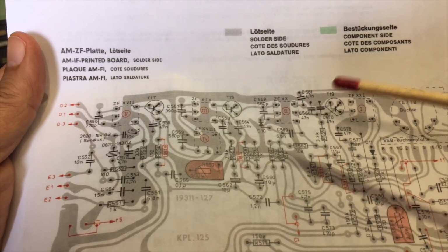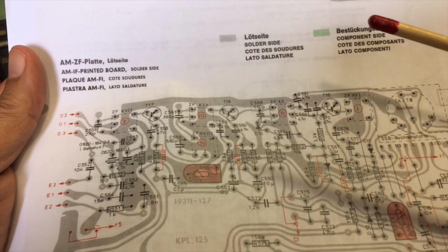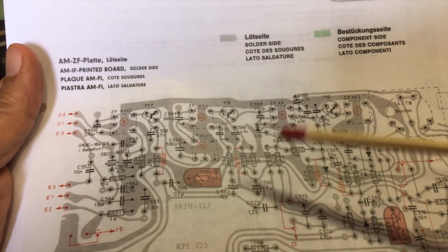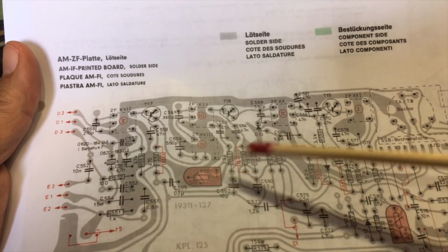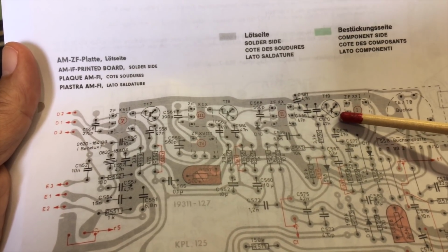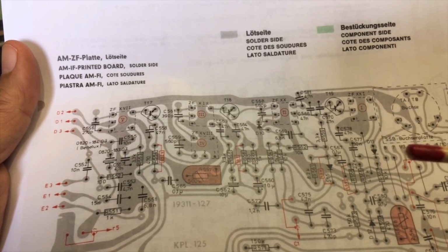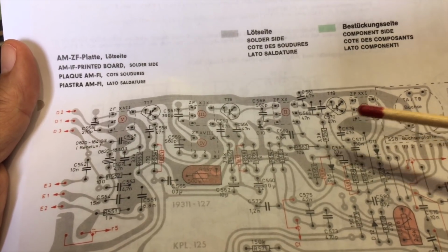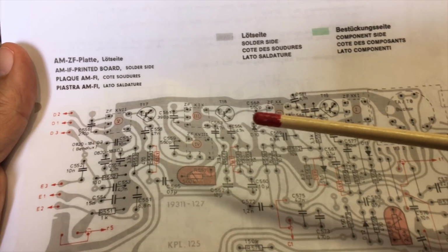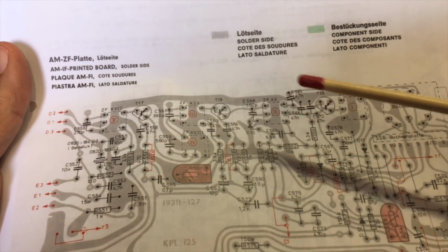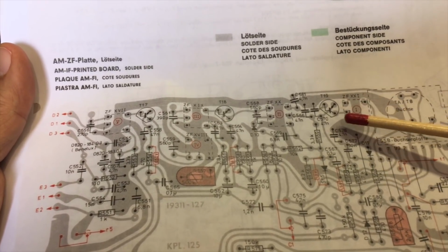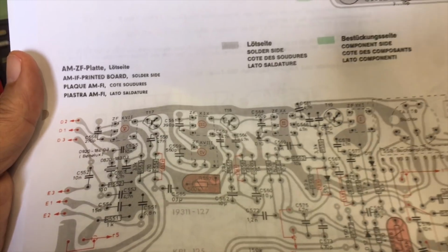They do tell us something else. They tell us to adjust for maximum and for symmetry. Now, I wanted to know what signals I'd be getting out of here anyway. What signal will I be getting at the collector of transistor 19? If I feed a carrier in it, do I need to modulate it? It's not that clear. They do say that you modulate it with a lower than 1000 hertz signal, but is that what we are seeing at the collector? So I decided to try it out.